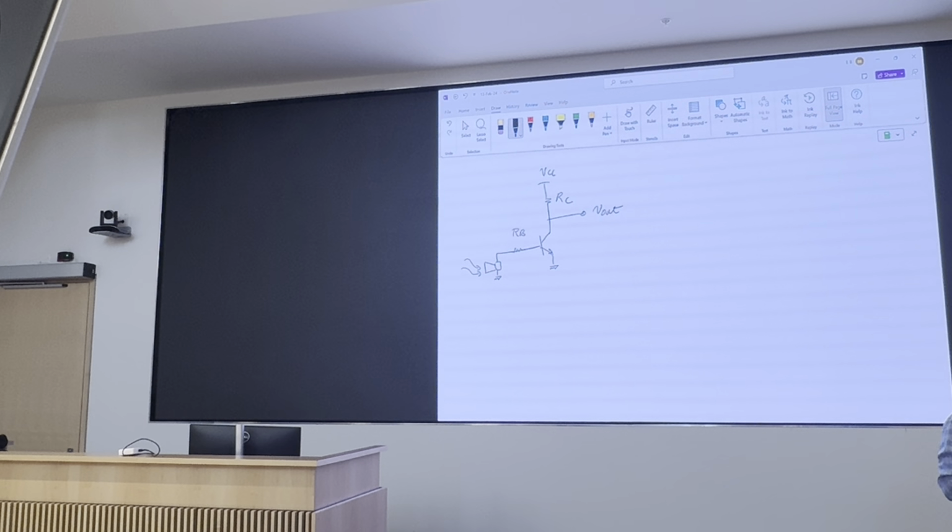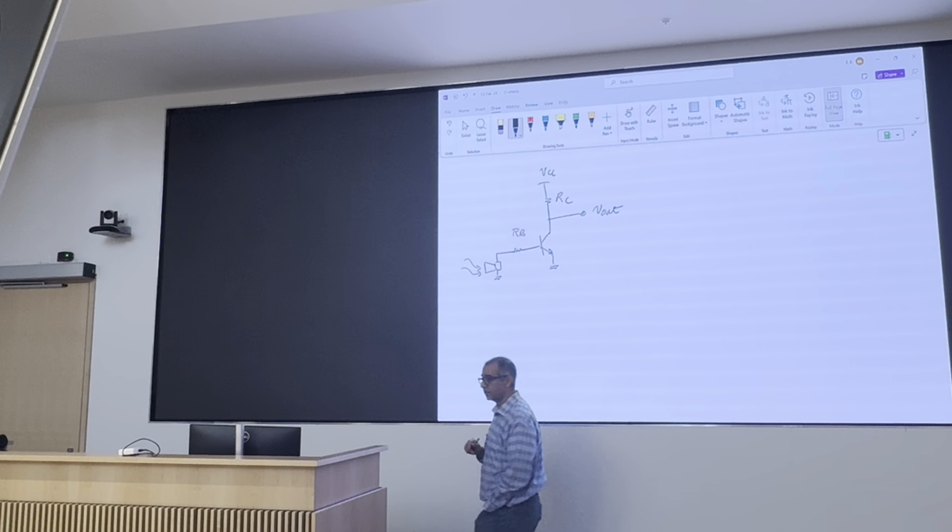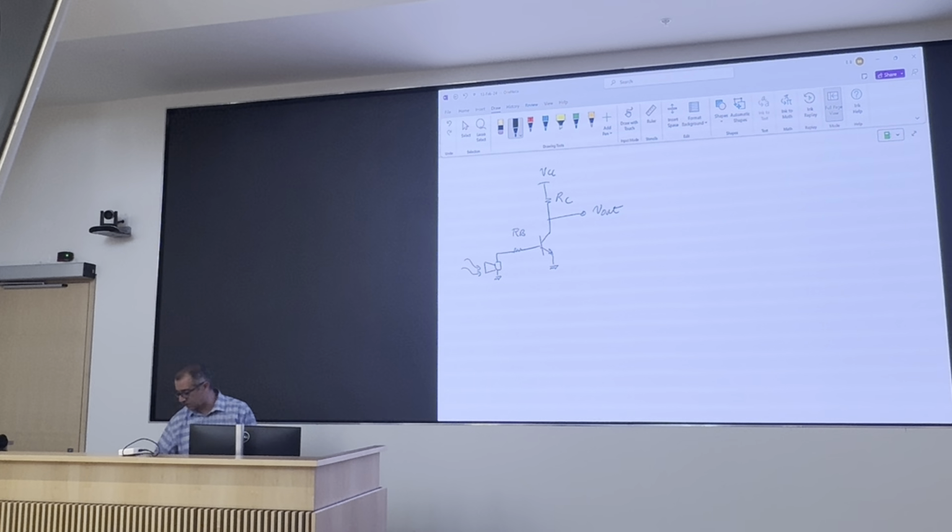In terms of the output of the speaker, you would have to overcome your diode. So that means every time you go below 0.7 volts, it won't be active. If you're producing millivolts, what happens? It won't be active, yeah. Your diode is not on, right?